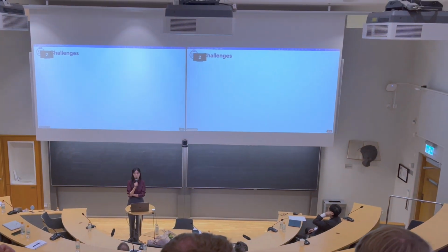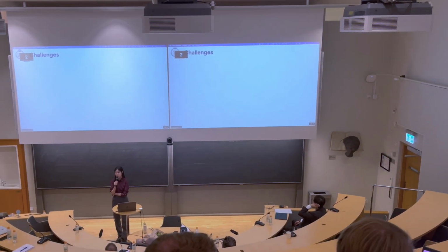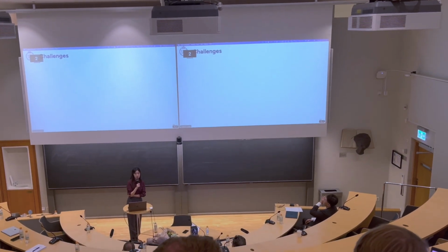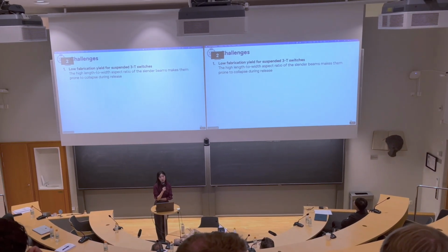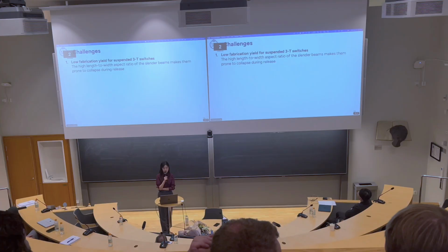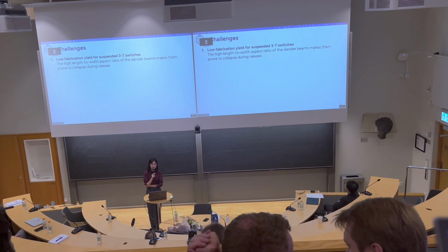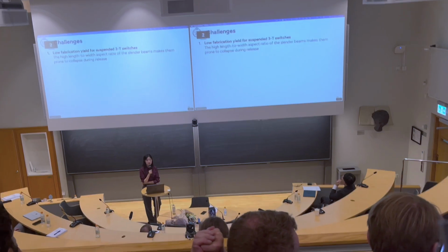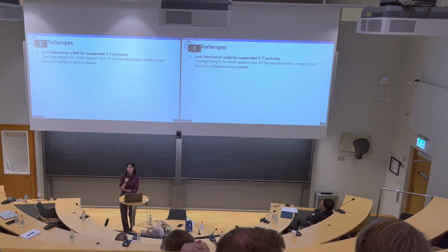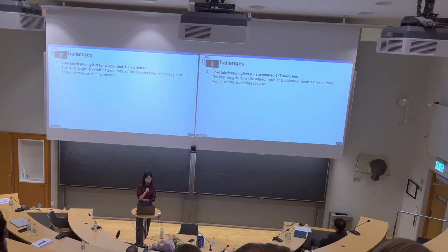So apart from the achievements, we also have some remaining challenges that we need to address before we continue our work. The first one is the low fabrication yield for the suspended 3-terminal NEM switch. Because of the long beam, the high length-to-width aspect ratio of the slender beams makes them susceptible to out-of-plane bending during the release etch.